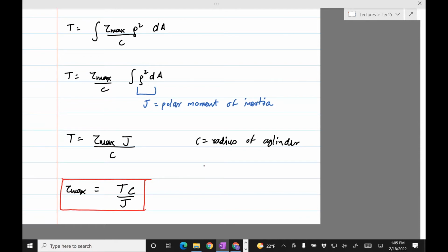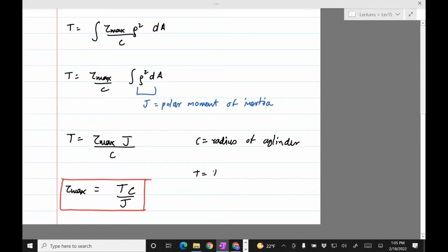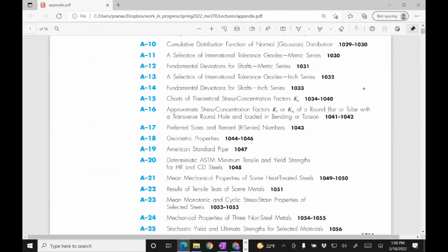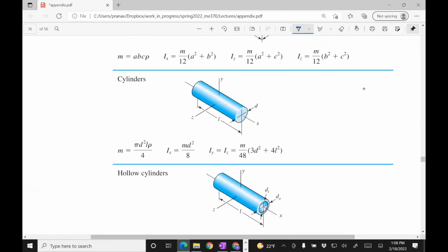Torque. It should be the same table we used for inertias, A18. Usually the most important ones are torsion of cylindrical sections. The reason it's important is because when you have a non-circular section and you twist it, you see that plane sections don't remain plane and they protrude out of the plane of the paper.